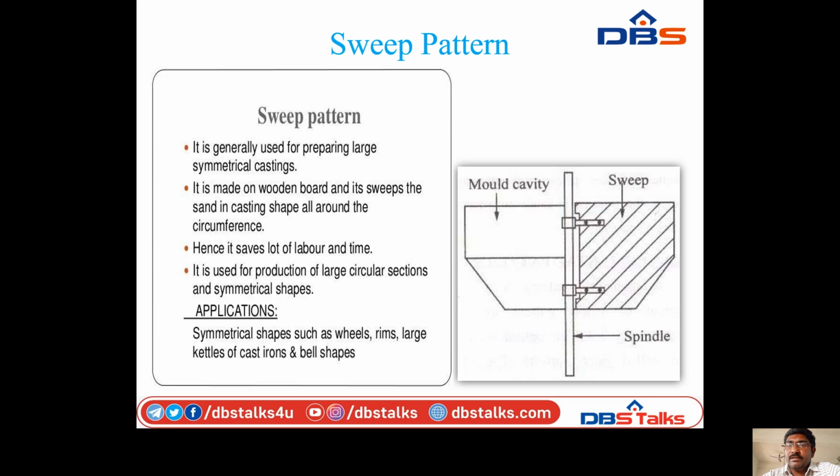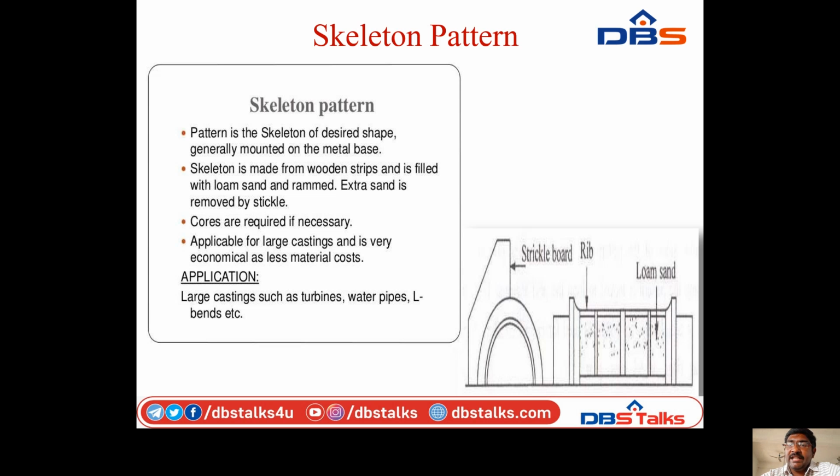So next, skeleton pattern. The skeleton pattern is a desired shape, generally molded on a metal base. The skeleton is made from wooden strips, filled with loam sand and rammed. Extra sand is removed by a strickle.